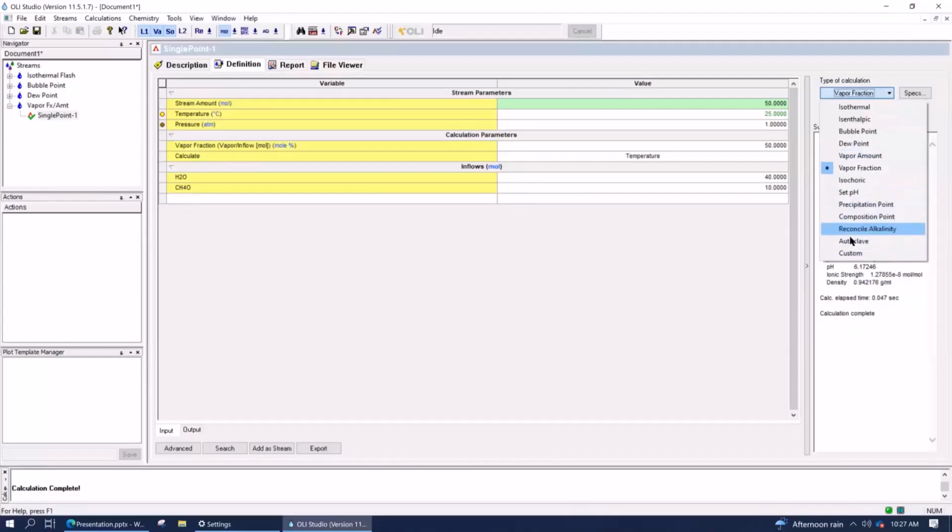So as we walk down this list, we're going to be doing a set pH calculation. And we're going to do a set pH calculation with carbon dioxide and with acetic acid. What you're going to see there is the buffering of the acetic acid or carbon dioxide to limit pH changes as I'm adding acids or bases. Look at this next one, and then the following one, precipitation point, and see if that's enough of the ionic chemistry for you. If not, then when we get to the water analysis, where we're actually adding cations and anions, including bicarbonate, acetates, etc., you can see that chemistry as well.